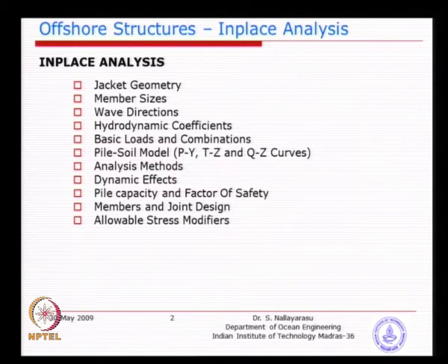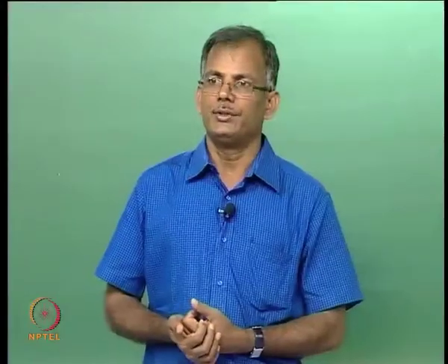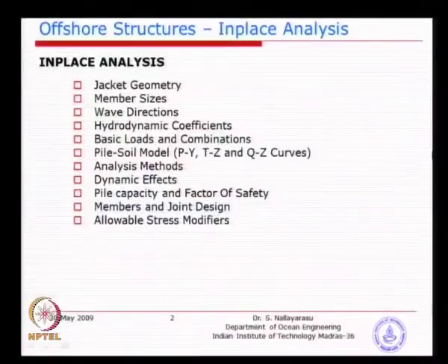So, we will go through one by one. I think we may require maybe 2 classes to complete this. Only, we will skip the hydrodynamic coefficients, because we will do that during the load calculations using wave and current. So, ultimately we do soil structure interaction, because this is a cantilever type of structure. So, we need to do a pile soil interaction, and then dynamic effects, because the wave loading is dynamic, and then we design the piles and design the members.